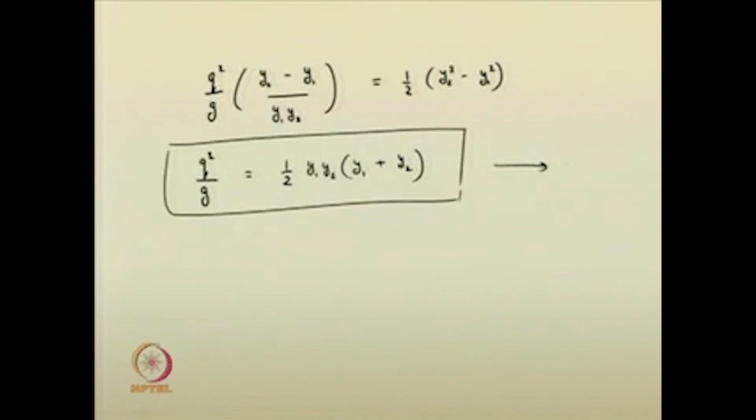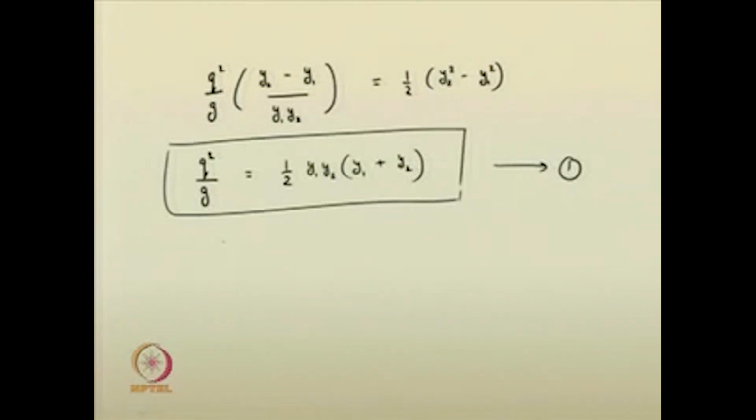So, you may be using them for many analyses today, right. This relationship, the discharge per unit width of the channel, you are now relating with the pre and post jump depths of water. Like that you are now able to correlate it. Just for your benefit, if you recall, in the rectangular channel section we had come up with a representation according to the upstream Froude number. We have come up with a relationship for the rectangular channel. We will see how it arises now.